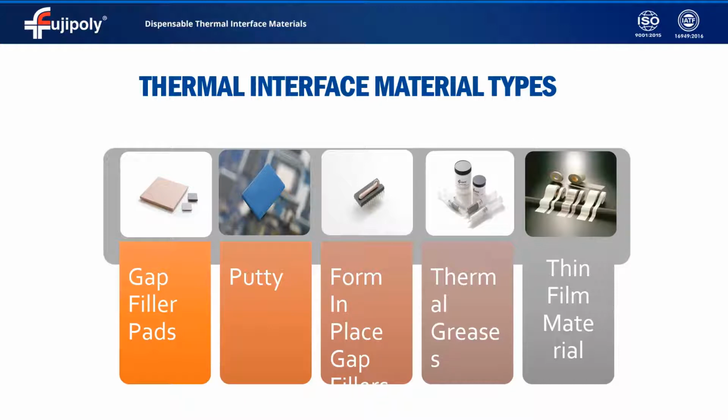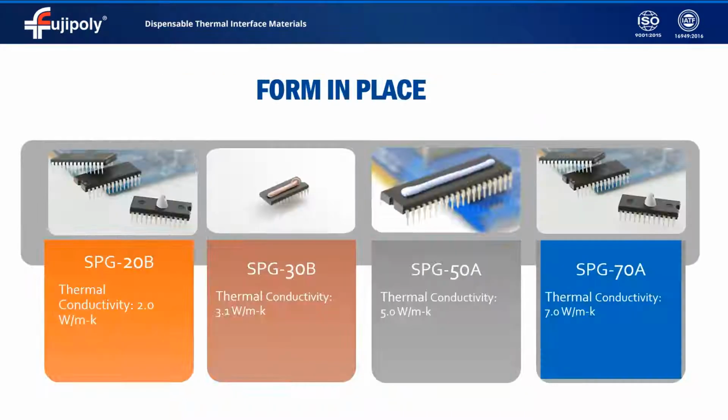Before we continue, I'd like to give the definition of a dispensable TIM. It is defined as a compound having a low enough viscosity that allows it to be pumped through the nozzle of a syringe, cartridge, or valve. Most of the materials are also thixotropic, so that they hold their shape or appear fairly solid until a sufficiently large shear stress causes the viscosity to fall and allows the material to flow.